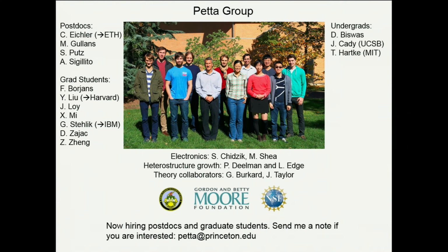And we'll see. I'm more optimistic about MOS. And if we needed to make a transition from silicon germanium to MOS, we could do it. We could use the same gate designs. But right now, I like the fact that our devices are buried. The electrons are at an interface that's 50 or 60 nanometers below the surface. It's clean. The mobility is high. And we have good control of it. The downside is valleys, and the valley splitting is 50 microeV. If it were 100 or 200 microeV, it would be big enough that we wouldn't care about it. And my hope is that we'll get it there, but there's more materials work that's required to do that reliably. Any other questions in the back?